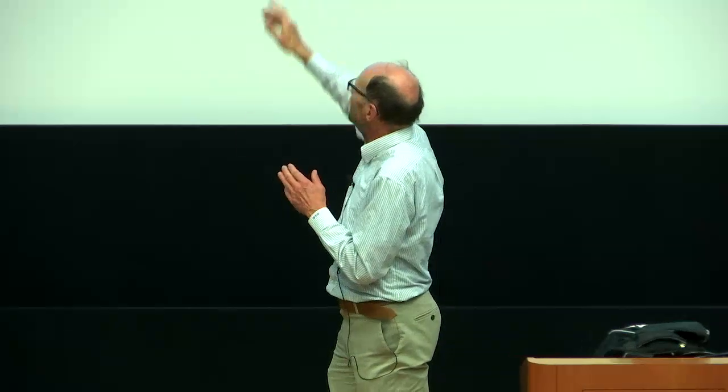And here we have a good justification to do so. We can always make the t-step very small. If we make the t-step very small, well, then the change in VC in every step is going to be tiny, and so the error we are making is very small. Incidentally, if you use a computer to solve numerically a differential equation, it does exactly this. We haven't invented this. The first guy, or at least the name attached to this, is Euler, another Swiss guy, but he lived in the 1600s, so it's not my fault. I wish.